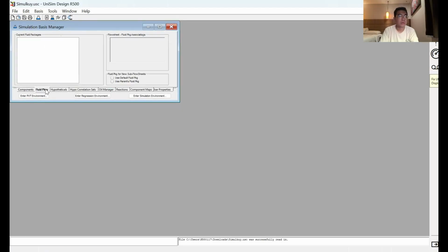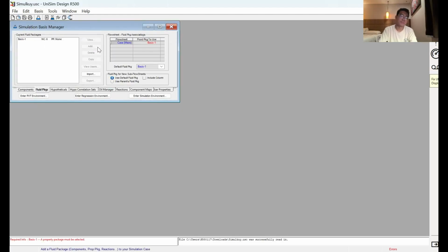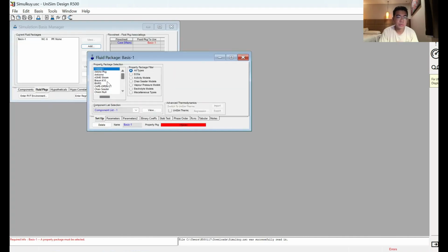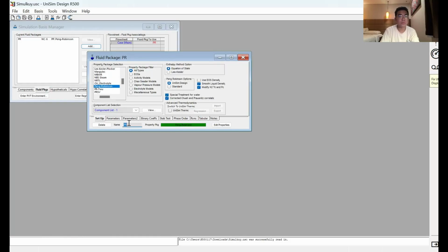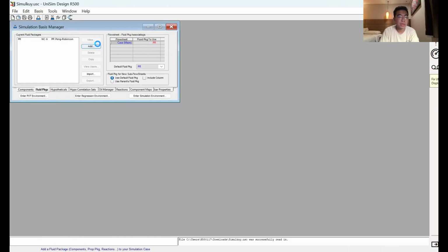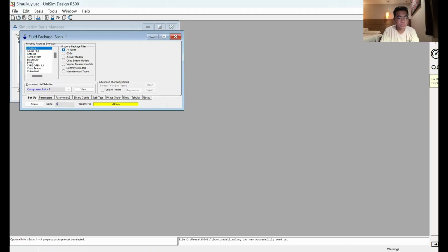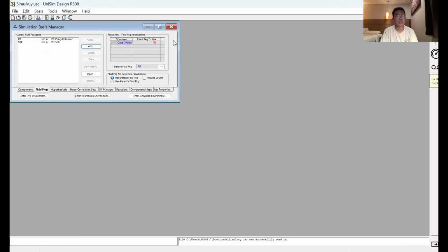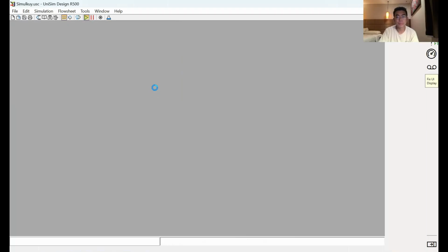Then the fluid package I will provide is Peng-Robinson and also create another one, SRK. Okay, nice. So the next step, we will go to the simulation environment.